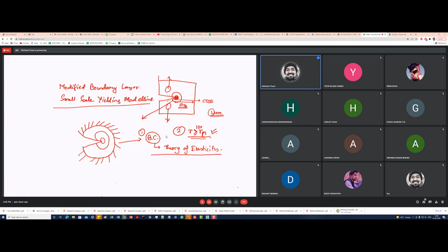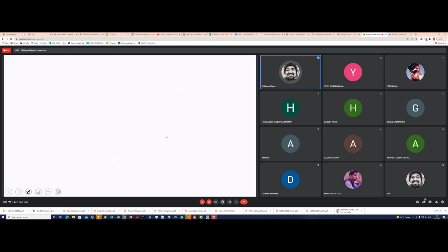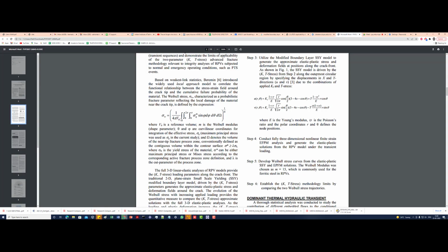And I will just tell you what the boundary conditions are without going much into the detail. So on this circle, one more decrement in the modeling can be done by making this circle a semicircle and using the symmetry. So instead of modeling the whole circle, you just have to model half of it, and on the boundary of this you will be defining boundary condition in terms of displacement.